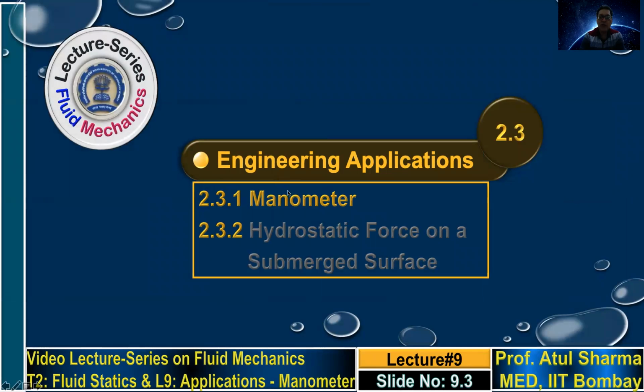The engineering application on manometers will be presented here, considering three types of manometer called the basic manometer, differential manometer, and multi-fluid manometer. A manometer is basically a pressure measuring device. The basic and multi-fluid manometers will be presented to calculate the pressure of a gas or a liquid in a tank, and the differential manometer is used to obtain the difference of pressure at two different points in internal flow situations.